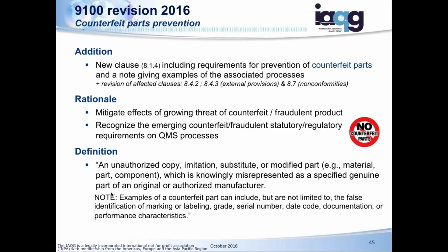The definition of counterfeit parts is an unauthorized copy, imitation, substitute, or modified part, material, or component which is knowingly misrepresented as a specified genuine part of an original or authorized manufacturer. So what's expected then is that you're going to, as an organization, look at the opportunities that you have for counterfeit parts, and then put measures in place to prevent those activities.